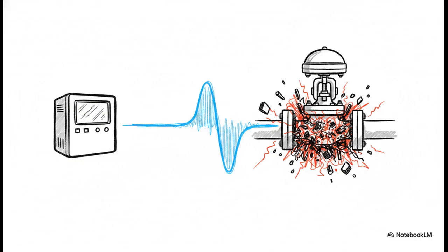Whether that's compressed air inflating a diaphragm, an electric motor, or hydraulics, that actuator is the muscle fighting against process pressure and friction. So, if your controller commands, say, 47% open, but you've got heavy friction and no smart positioner, the actual valve could easily be sitting anywhere from 40 to 55%. Always, always verify with a physical or feedback check.